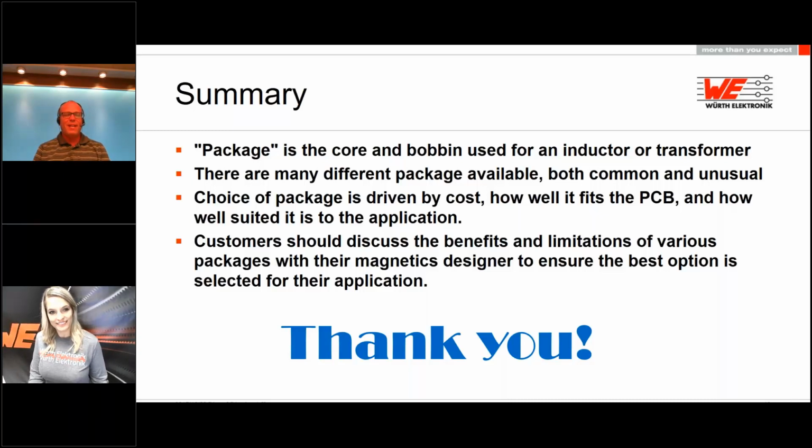So, yeah, I don't think I really answered the question. I personally use both. I probably use triple insulated wire more than I use margin tape, but it's probably a 60-40 split. So it really depends on the application, the cost objectives, and the package chosen. Yep. And when designing a transformer, there are just so many factors to consider.